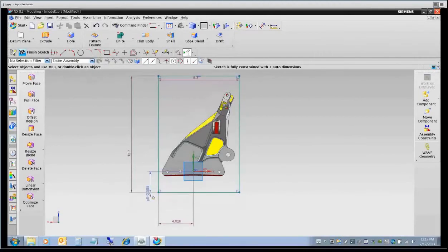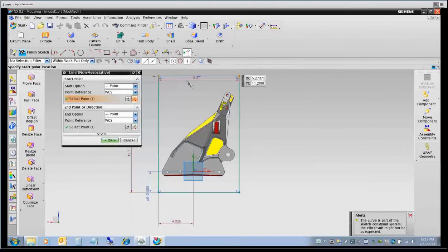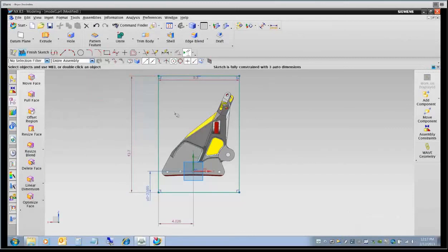Maybe if I needed an area on the bottom of the part for clamping, we'll click a little clamping cutout. Again, you can drive it by dimensions. I can grab a hold of the geometry, and I can just drag it. I can redefine it if we want with that part, right? So I can just pull it down and say, well, it's close to 12 inches. We should make it 12 inches, right?